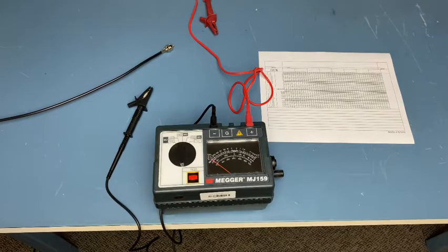To complete step 2 of this RPQ, you need to perform resistance measurements using a megger. A megger generates high voltage, which is capable of breaking down faults in the insulation. Failure to disconnect all equipment prior to megging could result in damage. To obtain accurate results, test all transmission lines and antennas separately.